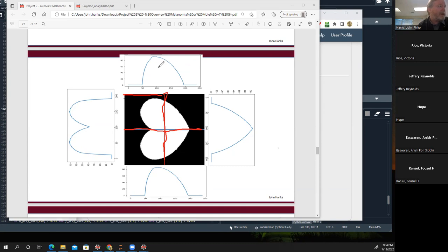And then if we correlated this signal with this signal, the correlation would be very close. It'd be close to 1, right? What the correlation function does is output a value between -1 and 1. So if 2 objects are correlated, the output is going to be a 1. If they're negatively correlated, you'll have a -1. If they're not correlated at all, if it was just random noise in both of these signals, it would be 0.